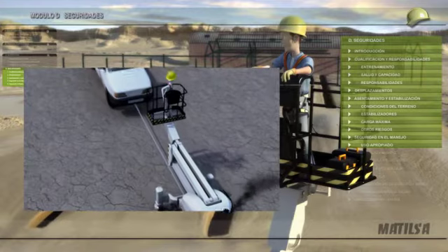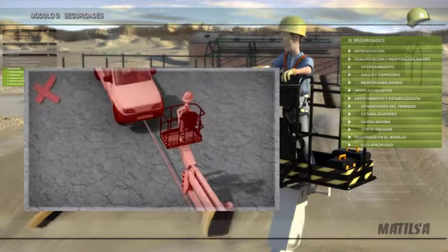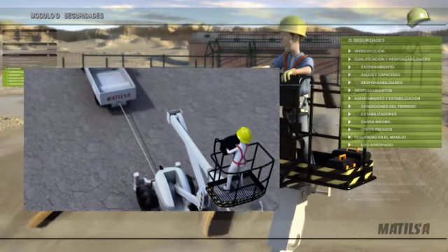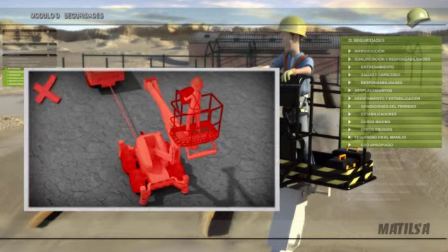Do not use the machine as a towing vehicle for other vehicles. The self-propelled platforms should not be towed away if the machine is not broken down. This may cause mechanical failures and constitute a danger for the person on the access platform.